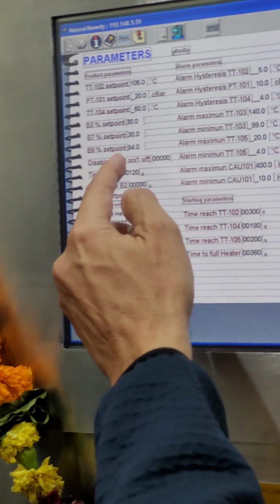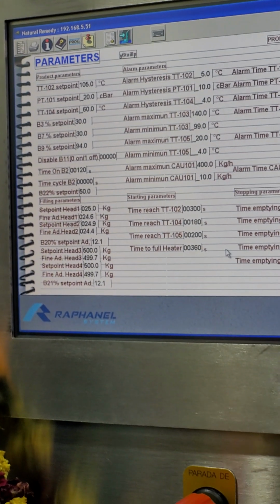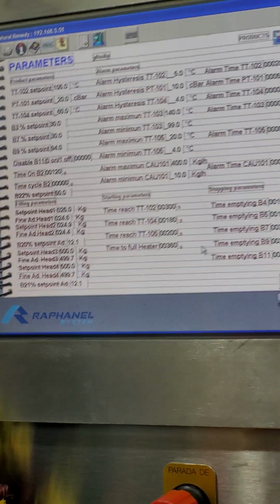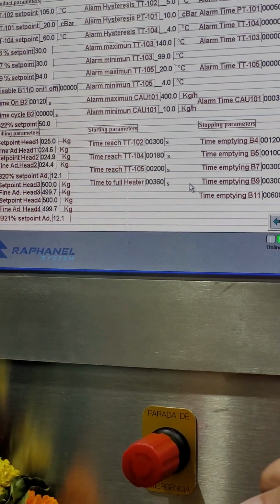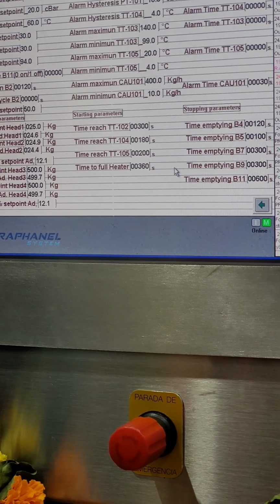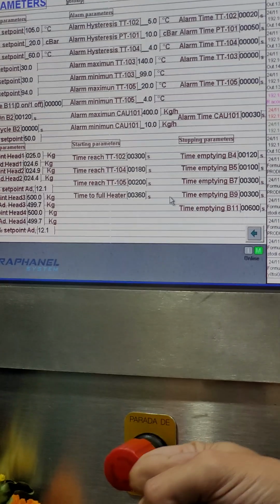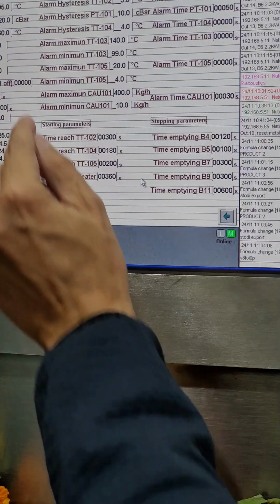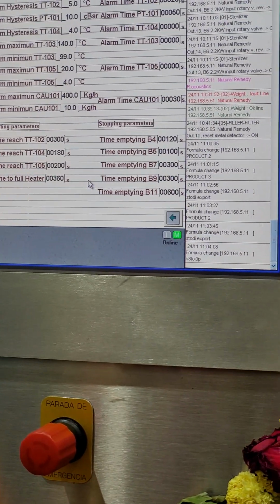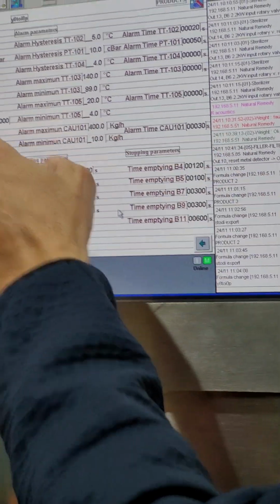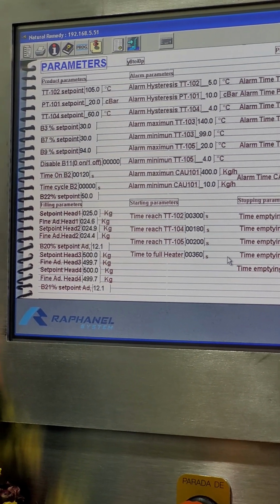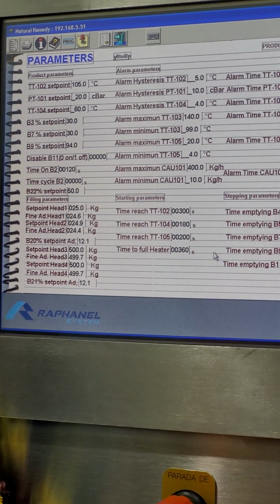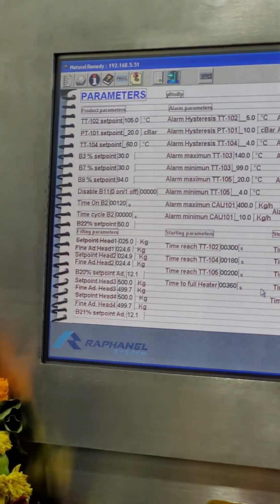If you want to make seeds, you have to stop the homogenizer, because if not, the homogenizer breaks the seeds. Remember, you have to open the homogenizer, remove the screen, and then switch it off. Because if you switch off but forget to remove the screen, all the material gets stuck there.